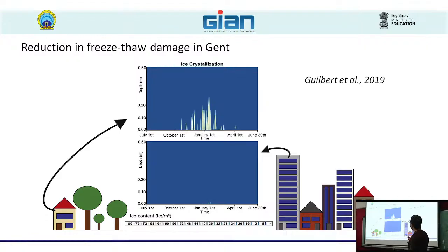That's the ice crystallization, all this moisture that goes inside the wall. We can check, for example, this is a rural area and this is an urban area. It means that in an urban area you have less of a problem. The building will have less because of the urban heat island, because it's always adding a degree. So you will not have this cycle often. Even the material is different, yes, that's also true. But the fact that you go from positive to negative happens much more often in the rural area. In the urban area, because of the urban heat island, adding this degree, it will not go down.